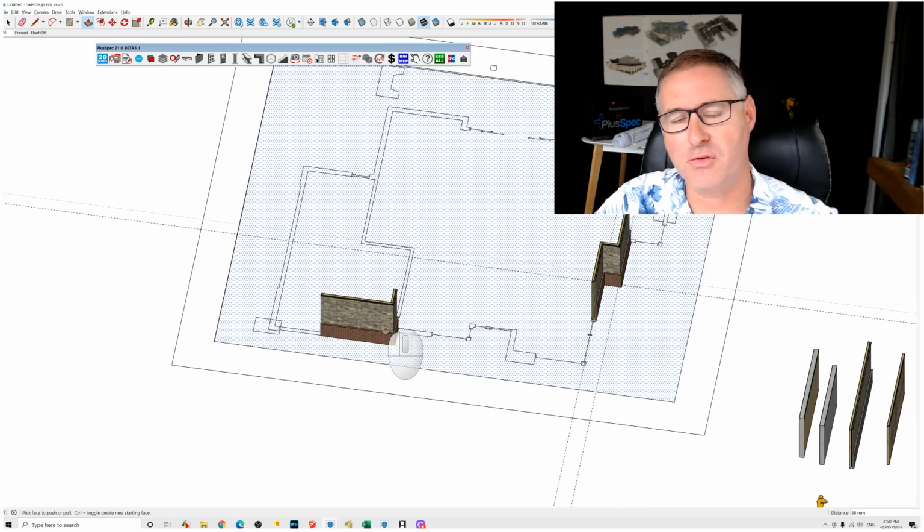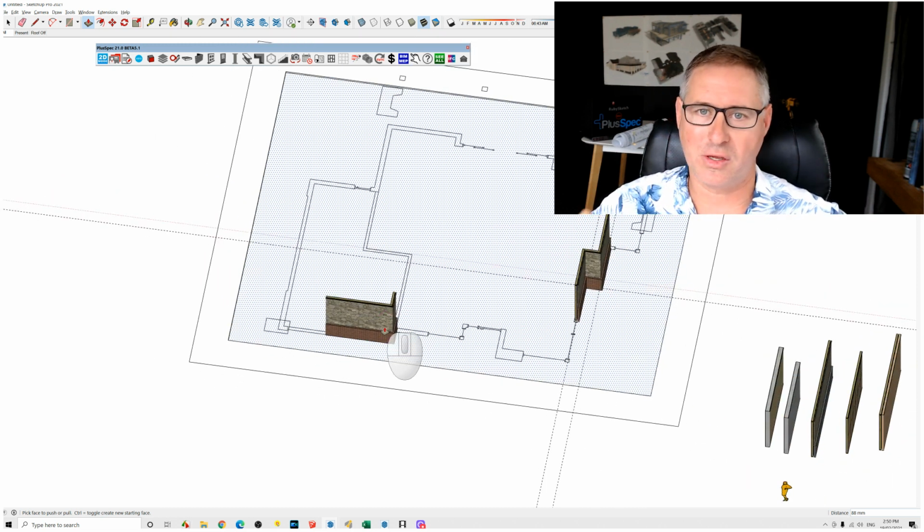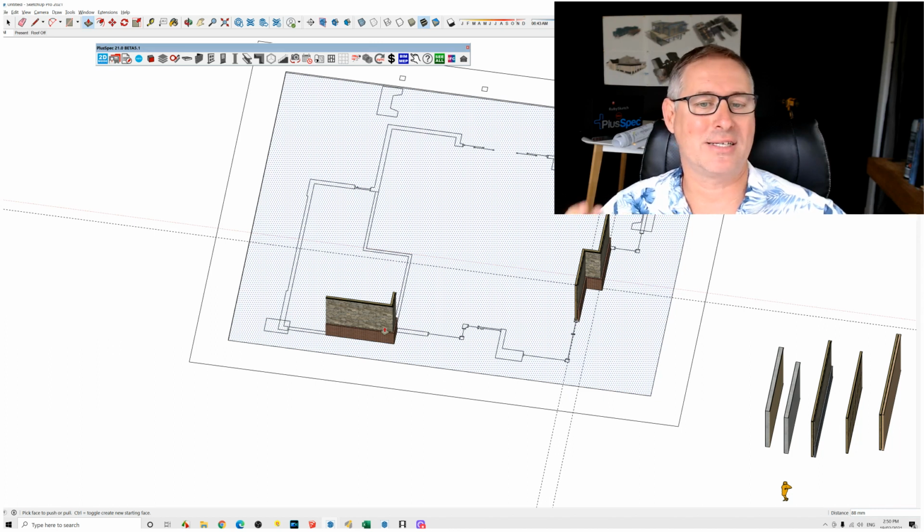at the time when you've actually put your roof on. Because if you go and draw up a conceptual design, do all of them in a solid wall that you think is 11 inches thick, and you go and put a roof on, and then you go back and you change the thickness of the wall, the roof isn't going to be in the right place, and it's not going to be designed to suit the way that it's actually going to be built.